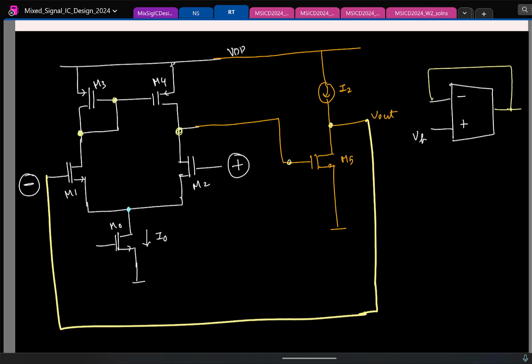And to see, let us say I gave you this, the simplest circuit. So let's just look at this and wrap up today. How can you prove to me that this voltage is getting set to a point wherein the current in the transistor is equal to this? I am saying it is not getting set. How do you disprove me? Let us say the current in the transistor is higher. Then what will happen? This voltage will start to drop, which means the drain current will reduce. A negative feedback is there.